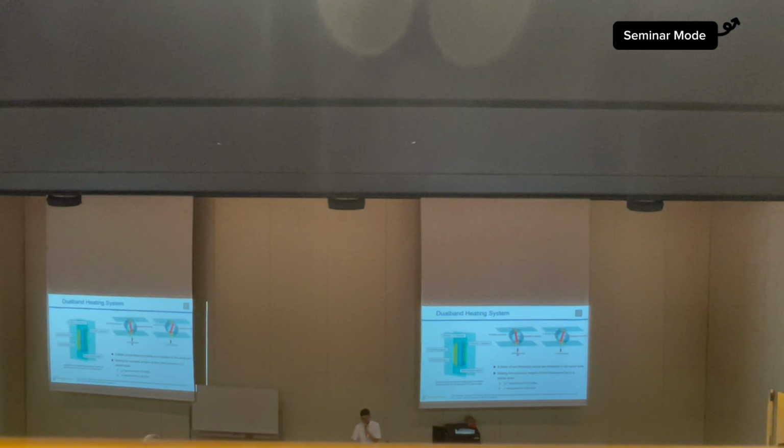If fields of two frequency bands are irradiated into the same area, to make the resonator lengths of both frequencies be of a similar scale, we use lambda over 2 resonators for 915 MHz, which has longer wavelengths, and lambda resonators for 2.45 GHz, which has shorter wavelengths.